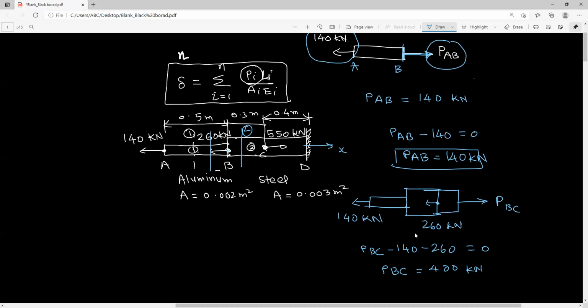Now the third part. You always have to see where your loading condition changes. If I take the section here, the situation is the same, right? So for the third section, you have to choose somewhere here, where your loading condition changes. Now I will draw the third free body diagram. I have cut the section at 3-3, so it will be something like here.